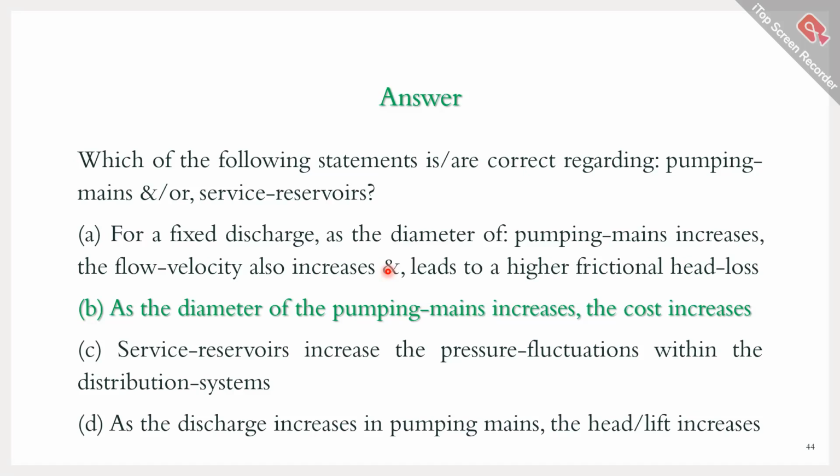That means the volumetric flow rate remains constant, considering the density of the fluid remains constant, for an incompressible liquid like water, whose density doesn't vary much. A1 V1 equals A2 V2 through a pipeline where the water is flowing.